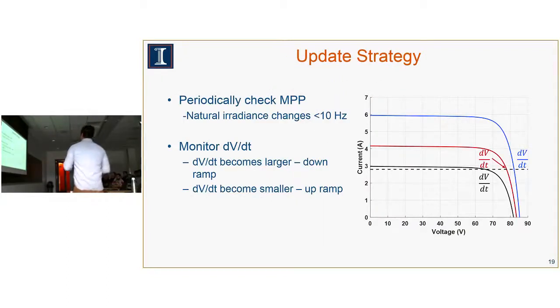And then just lastly, an update strategy. If you are off maximum power point, you have to check every now and then to see if the maximum power point changed so that you can update your values accordingly.